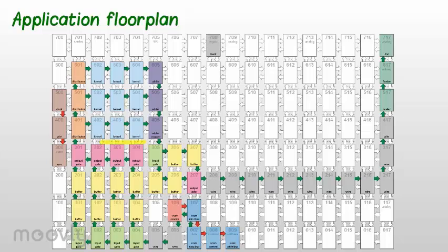The kernel reads individual pixel values, performs calculations, and sends partial convolutional results downstream into 3 nodes that sum the results up and clip the final result to an 8-bit value, as some kernels produce results outside of the 8-bit scale.